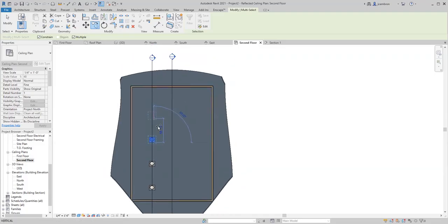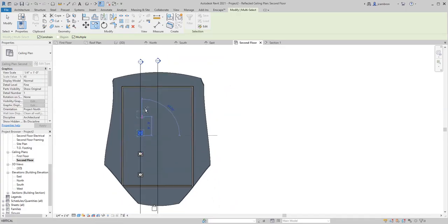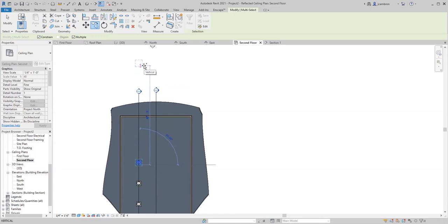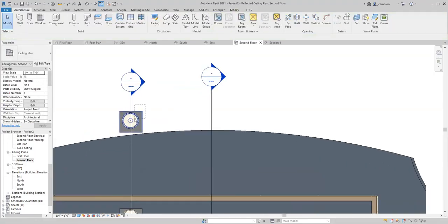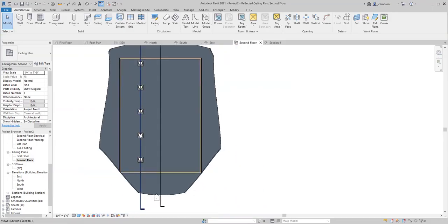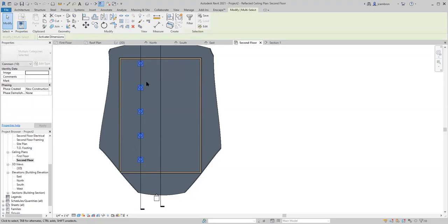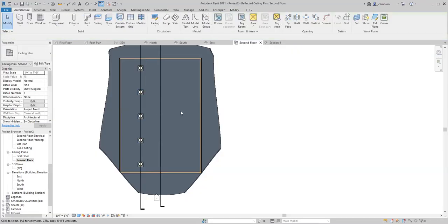Now, instead of having to move the cursor up every single time, what I like to do when I'm going to copy something in a row is move the object really far out. And now all I have to do is hit 10, enter, 10, enter, 10, enter, 10, enter, and so on, right? Obviously, I did one too many, so let's take this out. Now that's probably way too close to the wall. I could leave it, but I'm just going to do a cross window and move these down just a little bit. Click and drag, something like that. Okay.